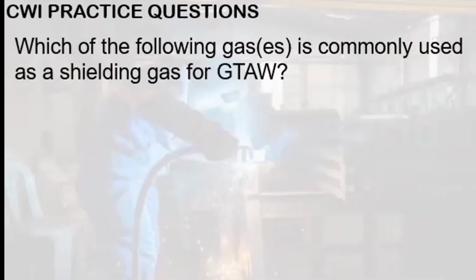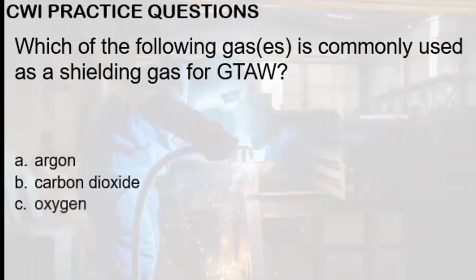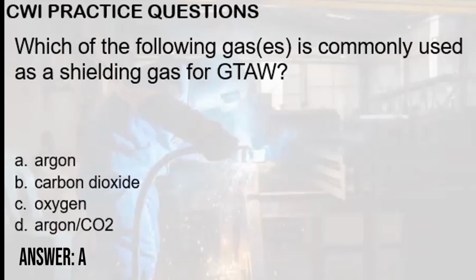Which of the following gases is commonly used as a shielding gas for GTAW, or gas tungsten arc welding, or TIG? A. Argon, B. Carbon dioxide, C. Oxygen, D. Argon CO2. Argon is the most common shielding gas because, amongst the choices, it is the only inert gas, but it is also the cheapest among all the shielding gases. Hence, it is the most commonly used shielding gas. The answer here is letter A.